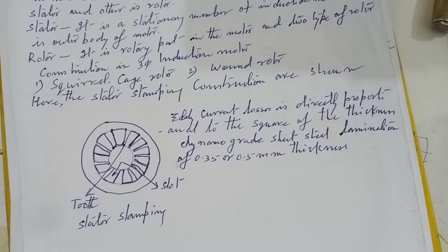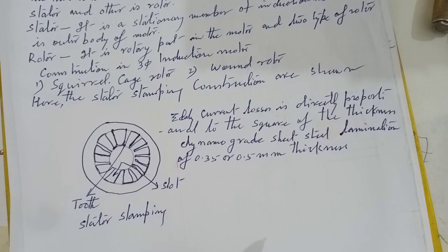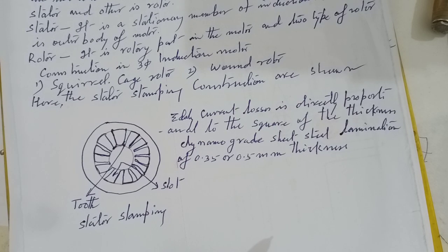For small size motors, punched rotor laminations are stacked and fitted directly on the shaft. For large size machines, laminations are fitted onto the spider web arrangement on the shaft. Suitable bearings should be provided at both ends of the rotor, and the rotor must be properly balanced to avoid the danger of the rotor striking the stator.